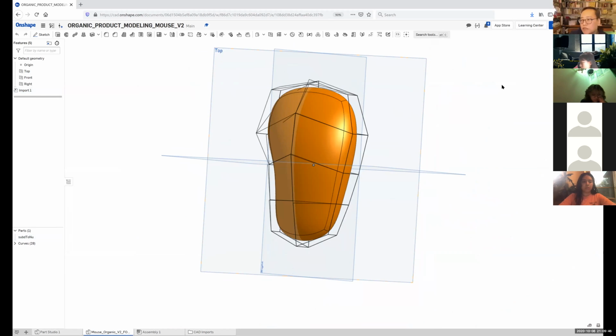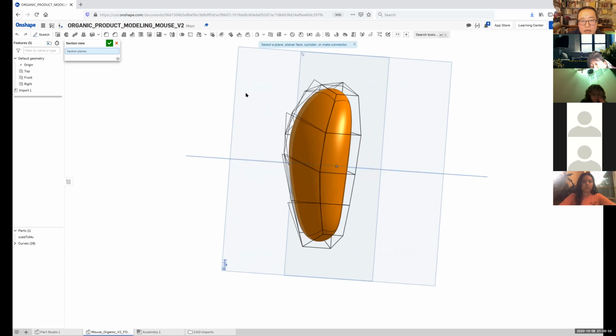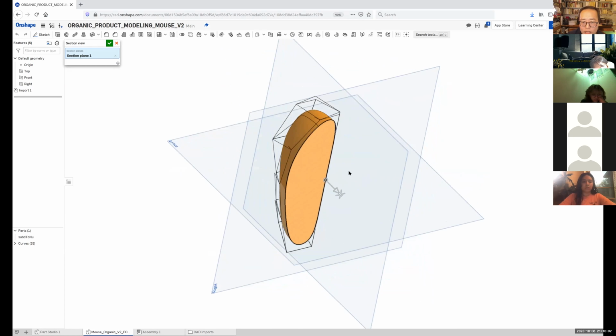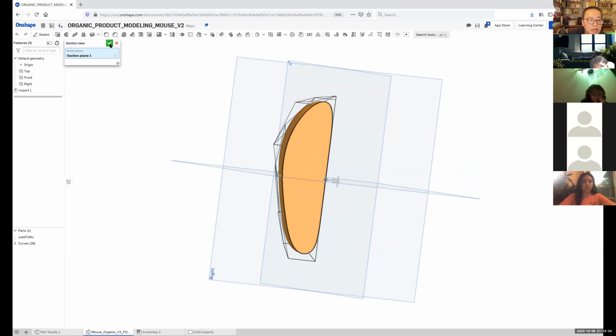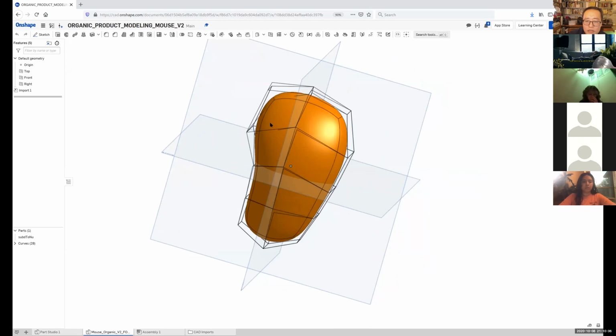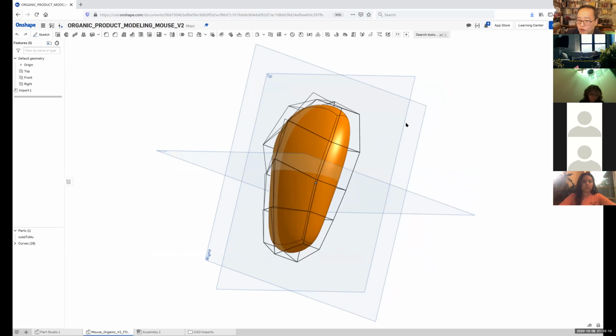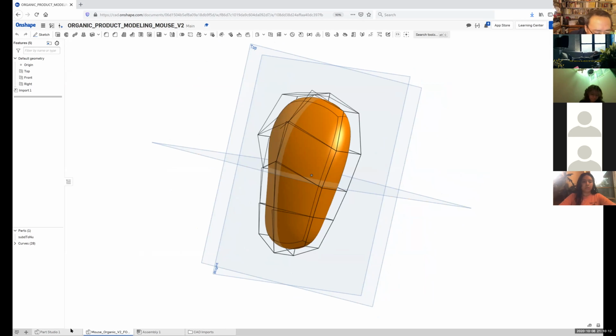And I believe that this is a solid object. You can verify that if you go into this view. Okay, I'm sorry, this is the view. So if you go section view and then choose the right view, yeah, so this is a solid, it's filled in, right? So it came in as a solid because the combination of these separate surfaces formed a closed volume. Okay. Now, check this out.